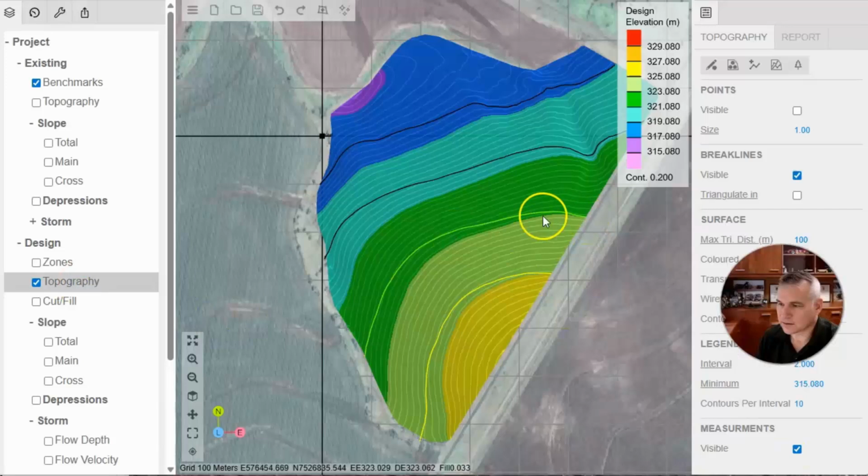So the solution here is to add contour banks. These are graded contour banks, so they're designed to catch the water as it flows down the hill. They'll catch it and take it down on a slight grade. So these contour banks are designed at a slope of 0.15%, so 150 millimeters in 100 meters, towards this edge, and then this grassed waterway will take the water down the slope. Because it's grassed, it can handle higher velocities.